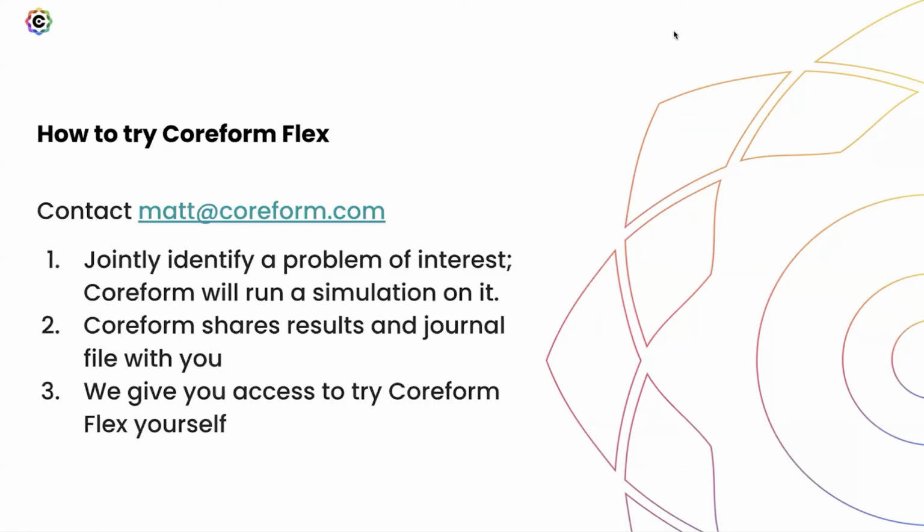And Sumit asks a question, Mike, that I think you kind of touched on: how fast or slow is the rate of mesh convergence for this method compared to traditional FEA? Okay, so it is a finite element method, and the rate of convergence basically is dictated, let's say we're dealing with sufficiently smooth problems, the rate of convergence is order p plus 1, where p is the degree of the polynomial being used in the function space. So if you have a linear finite element method, the order of convergence is 2. And with our methods, since they're higher order, the rate of convergence is much faster.